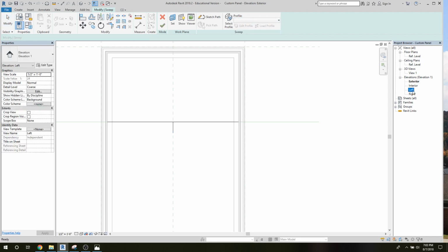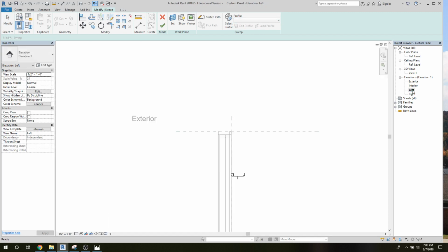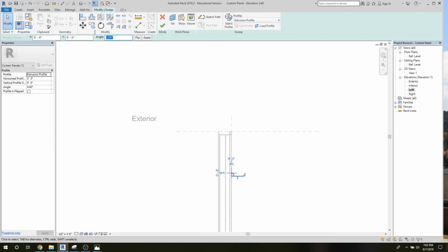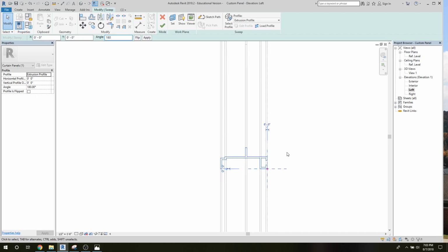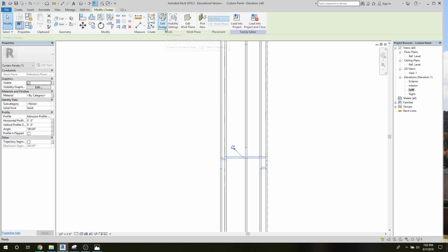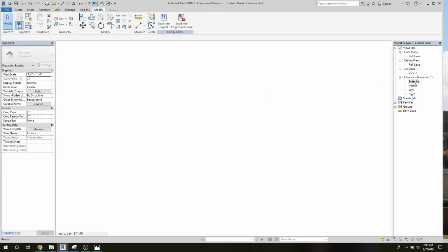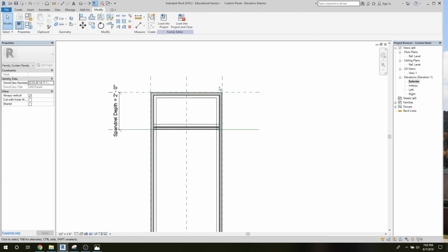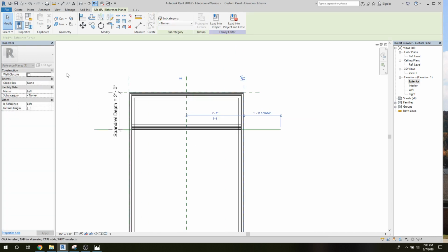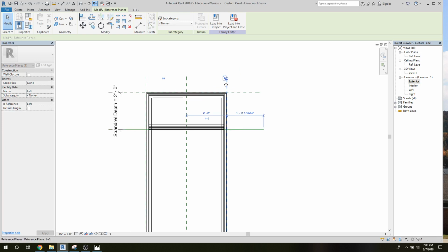And we'll look at it from the left side to see which orientation we have on that. Once again, we need to rotate it 180 degrees. And that one is facing up, and that's fine for the top edge of that spandrel. So we'll go ahead and complete that out. And we'll take a look at that from the front view. And now if we make adjustments here, we want to check to make sure that that expands out along with our complete window element.